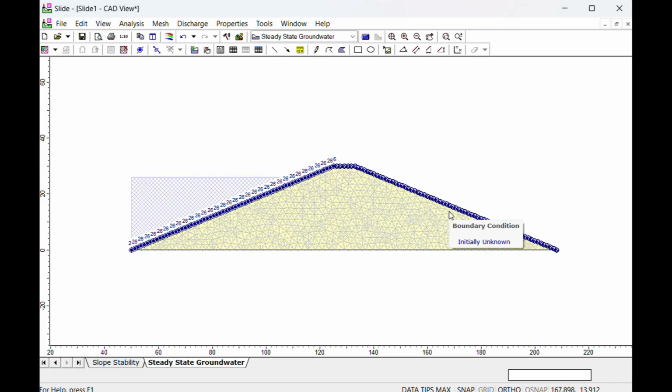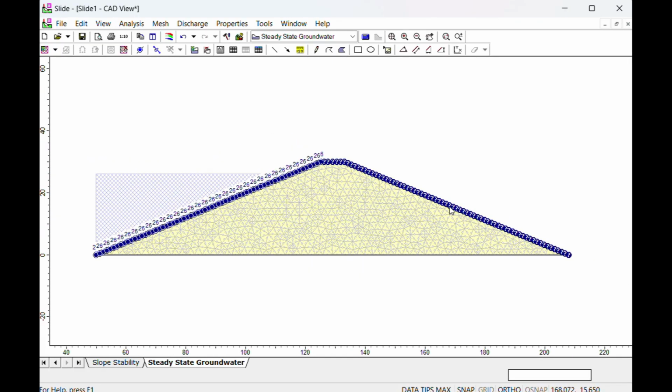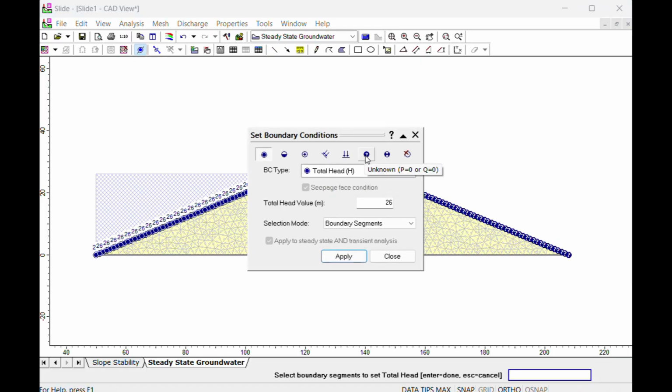But we do not know the seepage through the dam. Because of this, we cannot give a 0 boundary condition. That is how this question mark boundary is helpful. Whenever there is seepage or pressure above atmospheric, it removes the seepage. That means this boundary represents a filter. This means it collects the seepage.